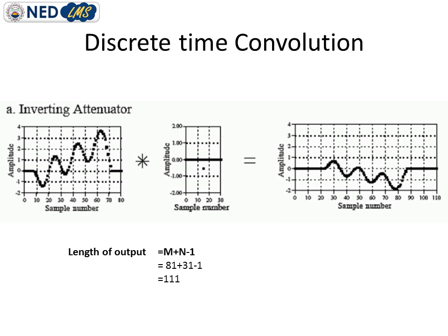It is very simple: add the length of the input signal plus the length of the impulse response and subtract 1. If capital N is the length of the input signal and capital M is the length of the impulse response, the formula for the length of the output signal is M plus N minus 1, as indicated in the slide.